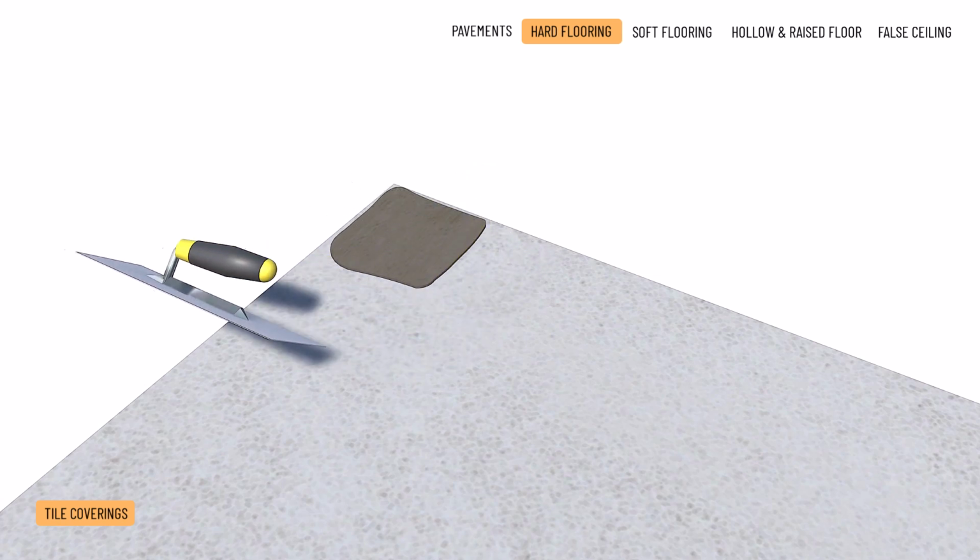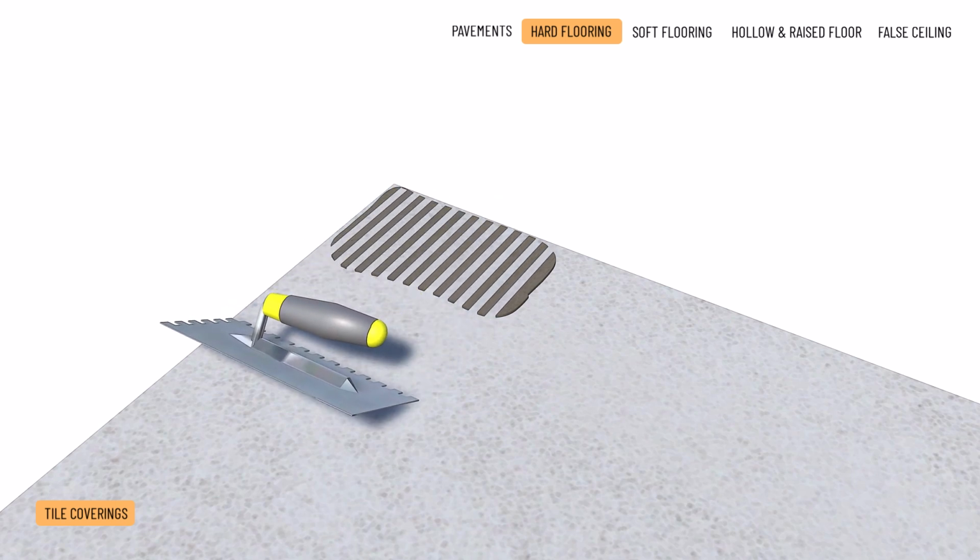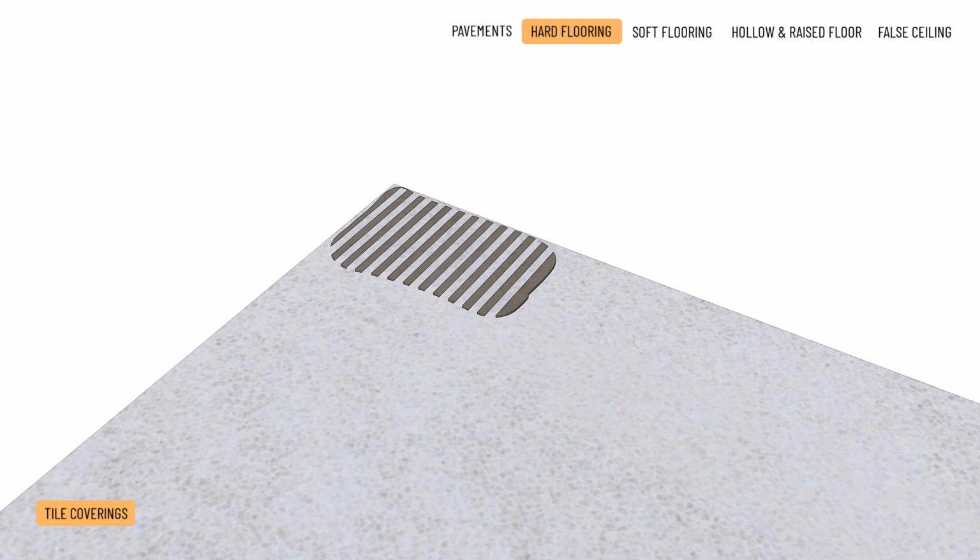Resin bonded, flexible adhesives are preferred when there is higher mechanical stress or greater temperature fluctuations, for example with exterior floor tiles. On a level subfloor, concrete or screed, the dry mix adhesive is prepared on-site and spread using a trowel or a plasterer's trowel. A notch trowel is used to ensure even distribution of the adhesive and uniform thickness.